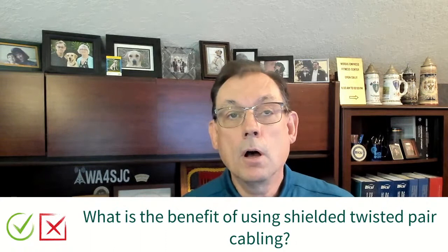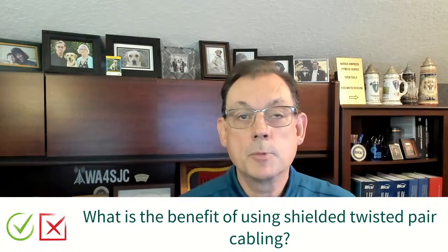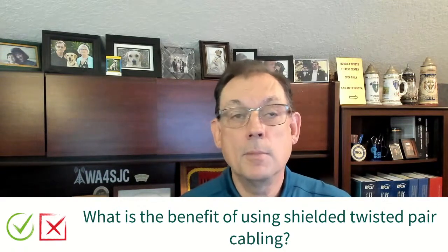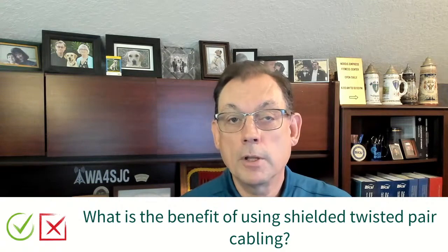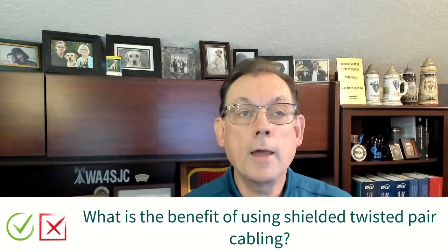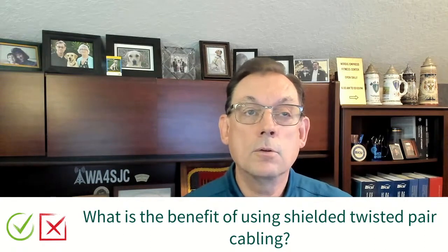Now, even basic unshielded twisted pair, especially once you get up to Cat 6A, is designed to mitigate that. Cat 6A was specifically designed to mitigate the effects of crosstalk, and alien crosstalk especially. So even in unshielded cables, the construction is designed to keep that noise at a minimum. Shielding is another way of mitigating the noise, and you can get it in a variety of cable categories. Shielded cable has been around for a long time. Even outside plant phone cables, if you still have a landline, have shielding built into them as well.